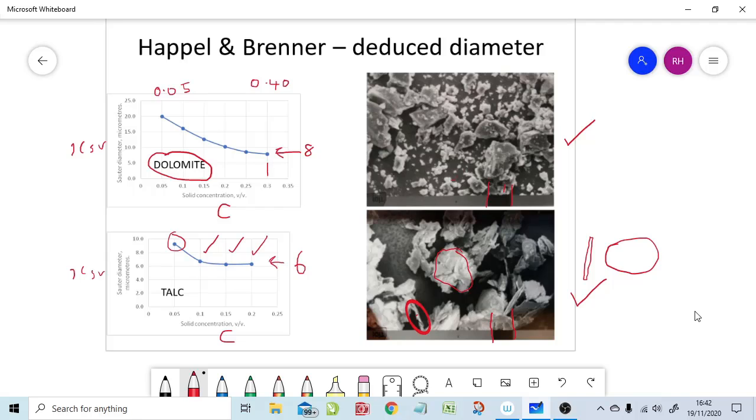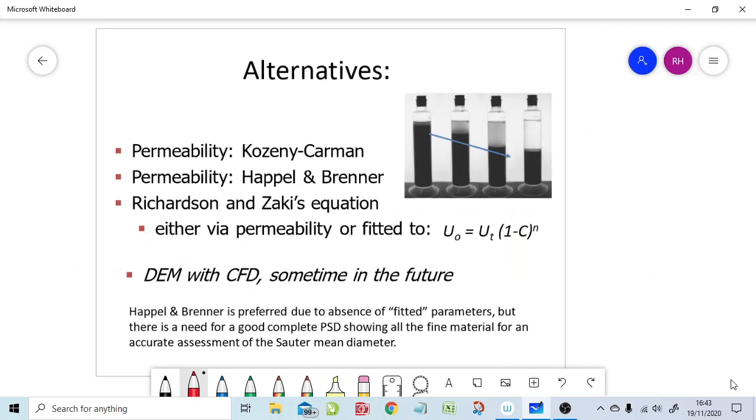If we're underestimating the settling velocity, and in fact the settling velocity is greater, then the whole thickening process should be a lot easier. So it's safe to stick with that underestimation of the velocity.